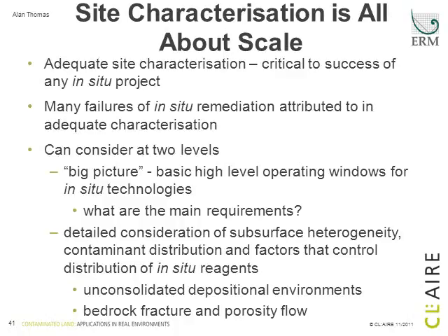And then when we drill down, we're really looking at a detailed consideration of factors like subsurface heterogeneity, contaminant distribution, factors that really control the distribution of in situ treatment agents, because ultimately, as I've said, in situ treatment is all about getting contact within the subsurface between your treatment agent and the contaminant that you're trying to treat. The geology is a significant control on this delivery mechanism, be it in unconsolidated deposits or within bedrock environments.